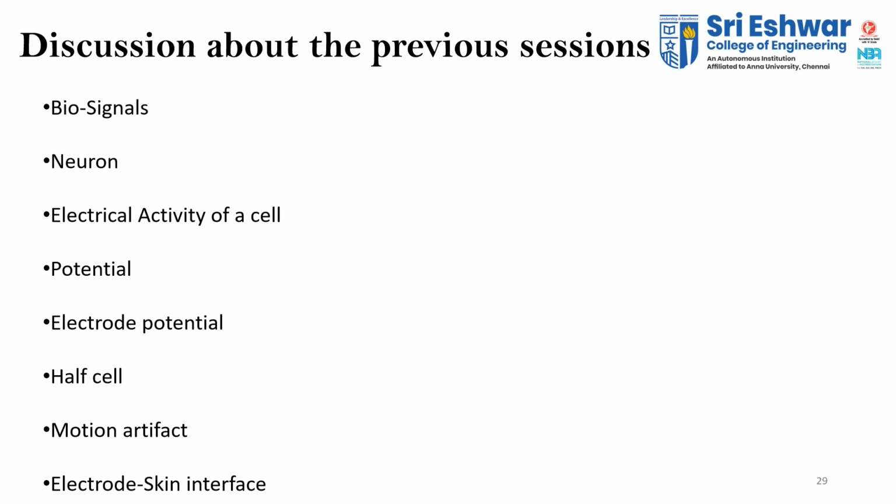So they will get into an improper treatment. That is why we are going to reduce these artifacts. The movement of electrodes and the movement of the patient cause artifacts. Also, the contact impedance on dry skin is about 100 kilo ohms and the capacitance is 0.01 microfarad. This is used for proper connectivity between your skin and your electrode.